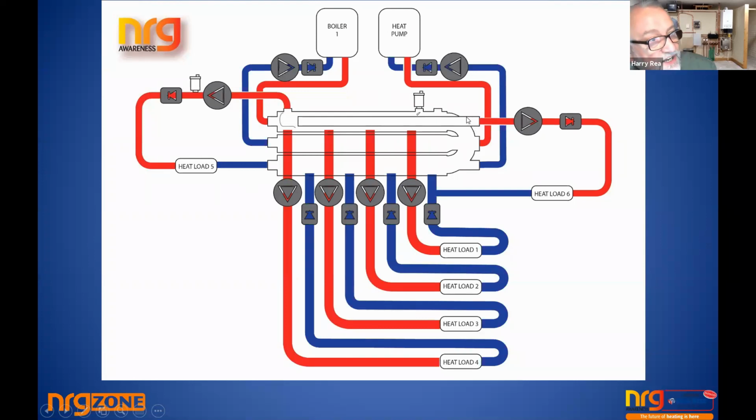If you wanted to put in an extra zone and you haven't got a return, there is no reason why you couldn't tee 2 returns together. So you can take advantage of the spare flow and still give yourself 2 boilers and 6 zones, even though now you're using it in a completely different way. You might want to use this for a cold feed or whatever. The point here is you're not stuck with the number of ports in the manifold.